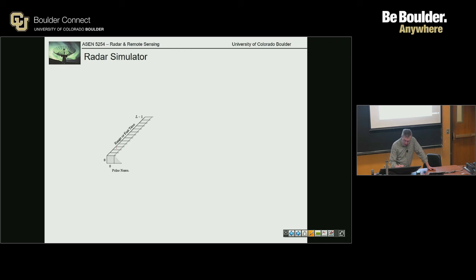So I want to just talk about the fast time. So this is transmitting the pulse. Transmit 1 pulse. And then each one of these gates corresponds to a range gate, but our TR was at a resolution of every 100 microseconds, and these gates have a resolution of delta T is equal to tau.